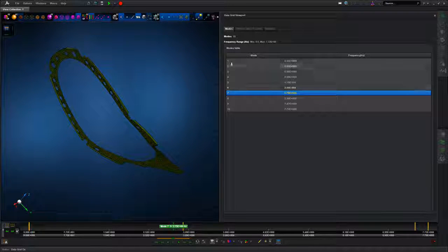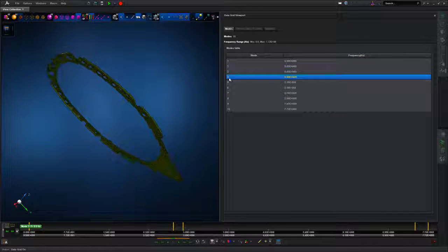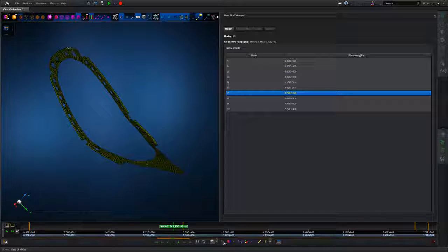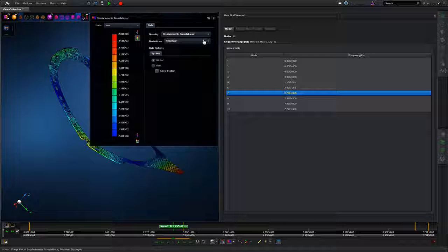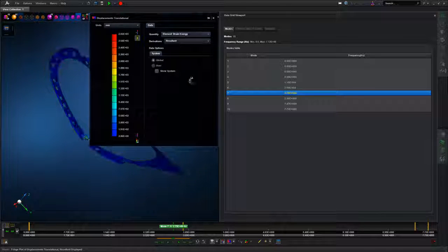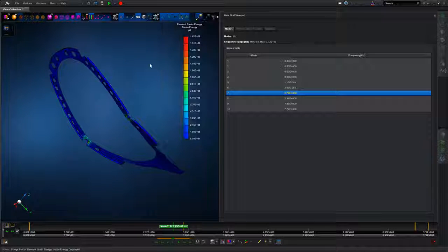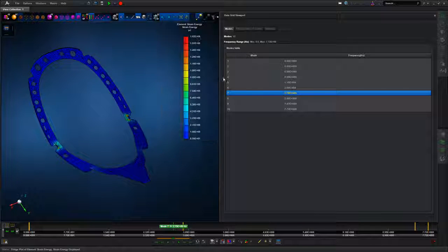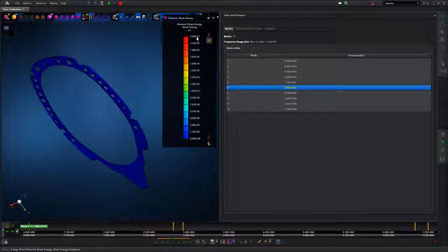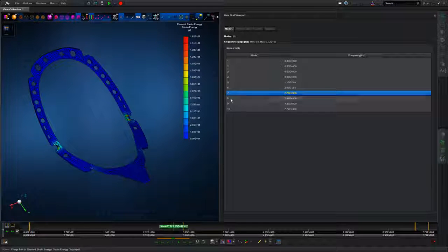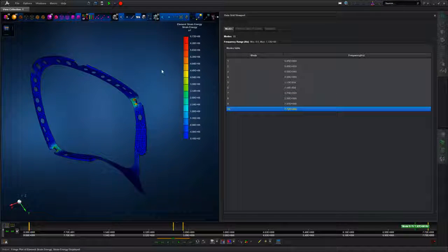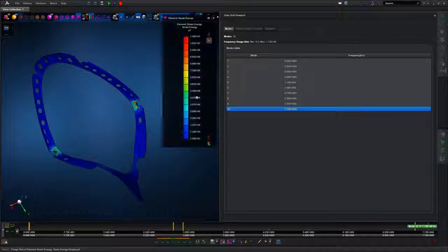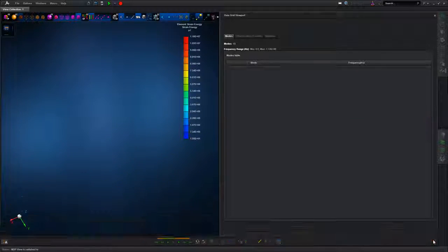We can look at fringe plots in terms of deformation and or strain energy to allow us to assess what's going on. So we can see here, so turn the fringe plot on and switching to strain energy, and we can see the 7th mode, which is the first elastic mode again, shows a sort of hinging effect where we've got a lack of stiffener in the overall model, and we can cycle through each discrete mode and make sense